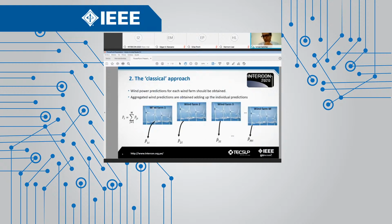What is the classical approach? The classical approach is to make wind power predictions. I'm talking about hourly wind power predictions. Every hour you build a prediction of the power or the energy you can supply, mostly for 24 to 48 hours, up to 1 or 2 days ahead. Then you have to build a wind power prediction for each isolated wind farm. I'm going to explain briefly now how to do it. And then we just add them up. And this sum is your regional wind power prediction.